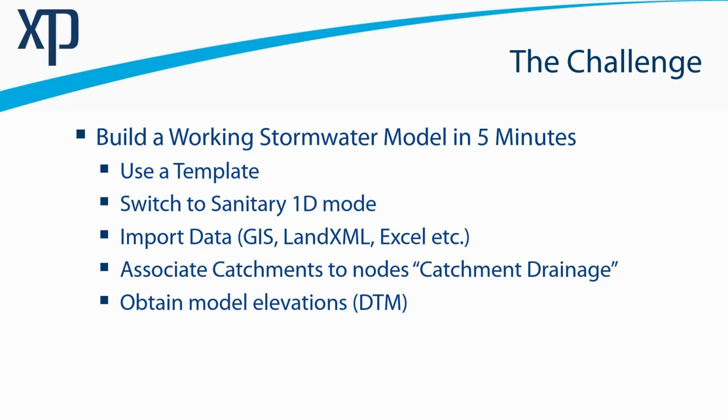And I'm going to set out on this challenge by using a template. The template's going to be key for me to have different things set up, like tables for viewing the data, etc. I'm going to switch to what we call a 1D mode or a sanitary wastewater mode. This is a new feature of the software that will shrink the complexity of the interface for those that aren't doing 2D modeling. For example, those things will be disabled or invisible, or it will just streamline.